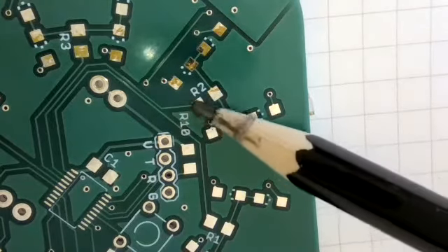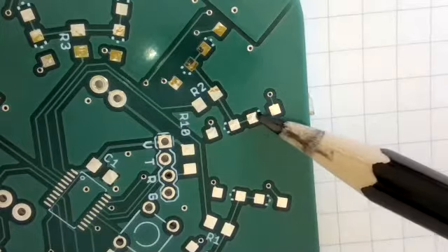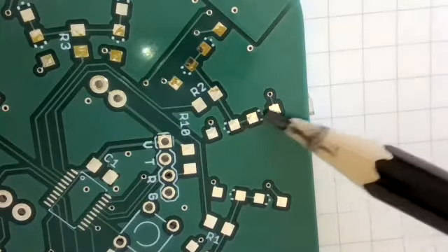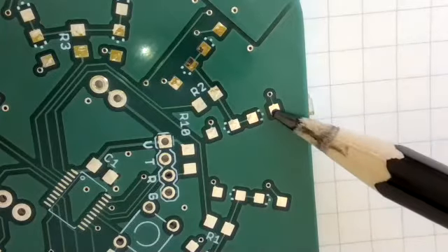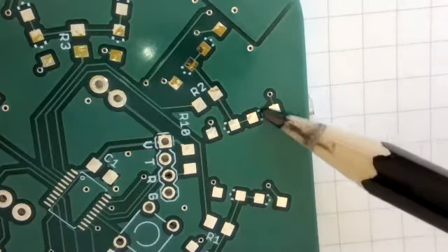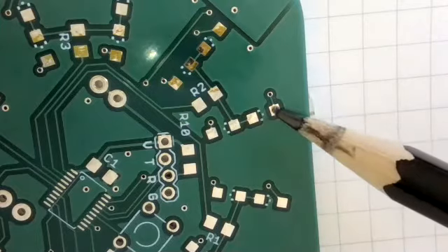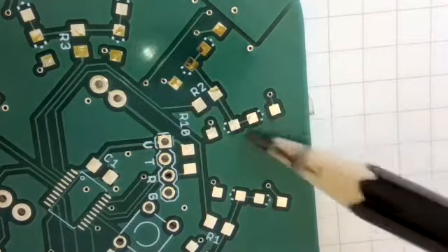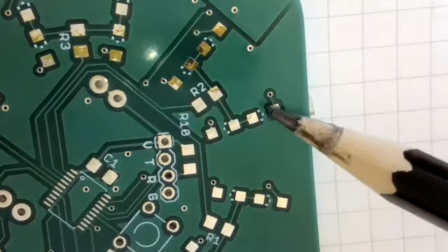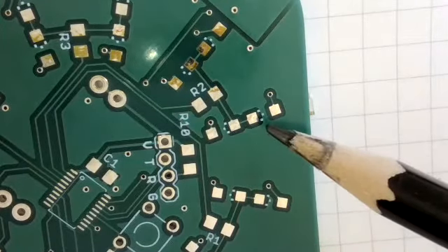And so now there's two ways that this can work, right? This value can be high, and this value can be high, in which case no current will flow. This value can be high, and this value can be low, it can be ground, in which case current will flow through this direction. Or also, if we make this pin an input, then this value can be high, and then this diode is effectively not connected. And so that's sort of our trick here.